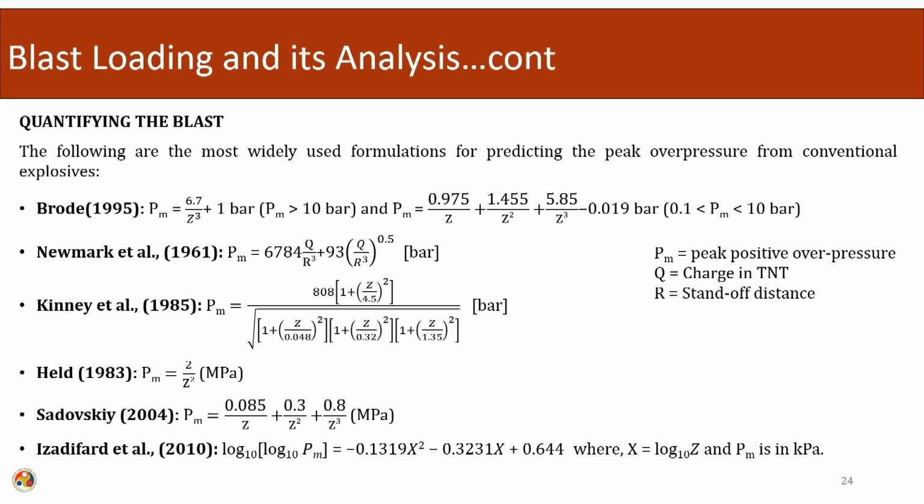So, blast quantification. To quantify the blast, there are different formulations proposed by different researchers depending upon the amount of data that was available to them at that particular point of time. So, there are many equations: to quantify the effect of the pressure, the time, the positive phase duration, the negative phase duration, depending upon whatever data was available at that point of time. Here we are showing some of the widely used equations.